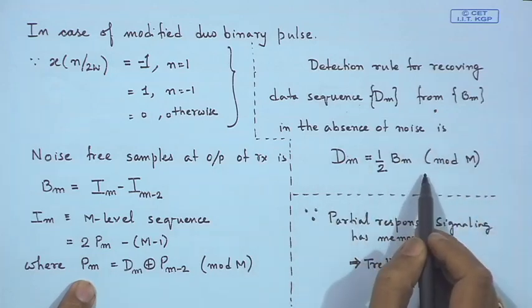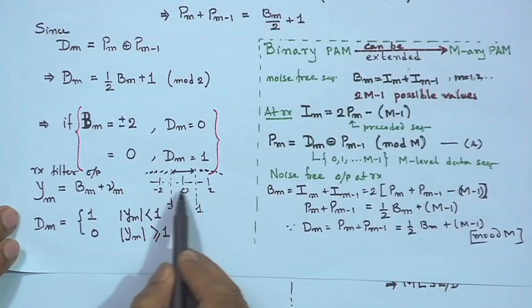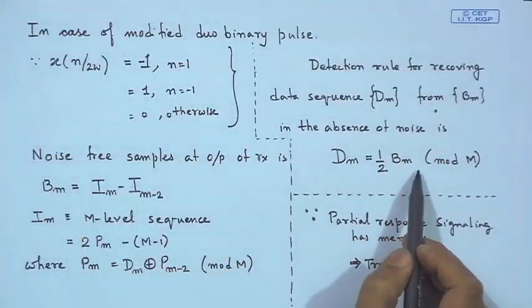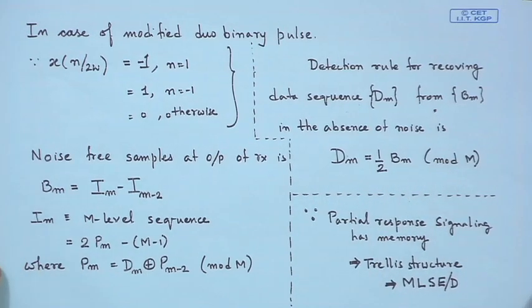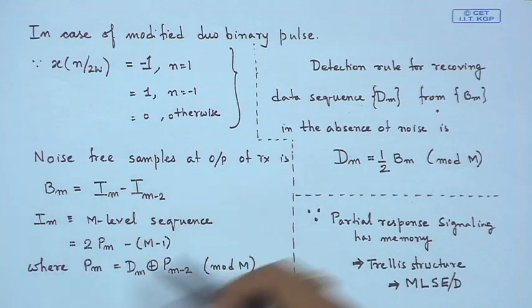With noise there will be thresholds like we considered here. So, similar to the thresholds that we had considered, we must consider thresholds in this case and would decode the received signal. So, as we stated in the beginning, all these methods are suboptimal because we are looking at symbol by symbol. The other way of recovering the signal would be to consider maximum likelihood sequence detection, or maximum likelihood sequence estimation, which we had described in an earlier lecture.